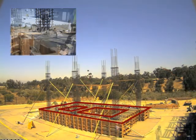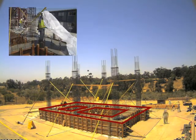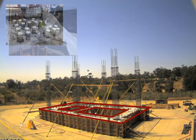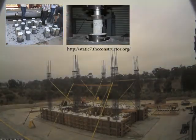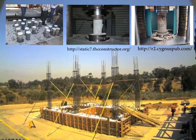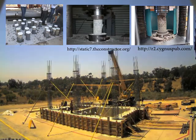Finally, the concrete is thoroughly covered with a waterproof layer in order to control and keep the moisture content preserved during the curing process. During the pouring process, samples of the concrete are poured into small cylinders, which are prepared for testing various stages of the curing process to assess the concrete strength. After 28 days of curing, the concrete should reach around 90% of its design strength.